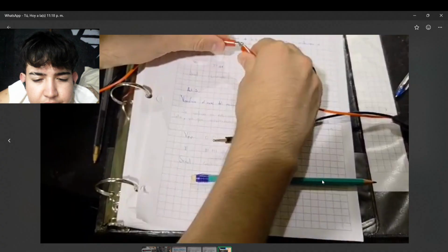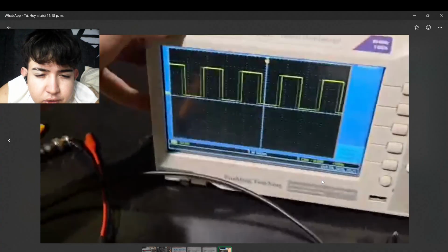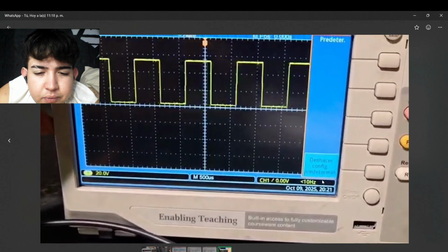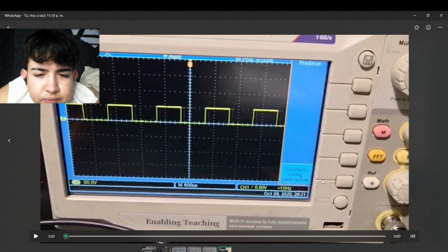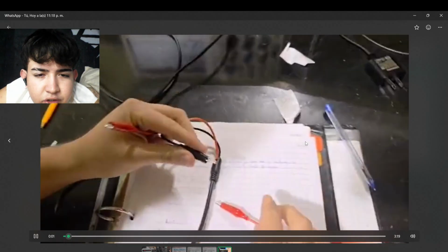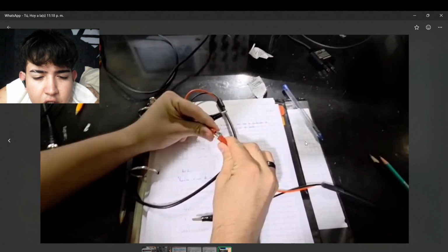The amplitude and frequency were varied in the generator, observing the following effects. Amplitude: increasing the amplitude caused the height of the wave on the oscilloscope to increase proportionally. Frequency: increasing the frequency caused the wave to compress horizontally, showing more cycles in the same amount of time.